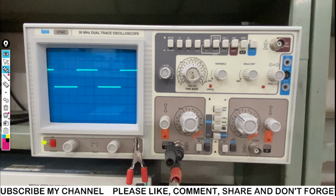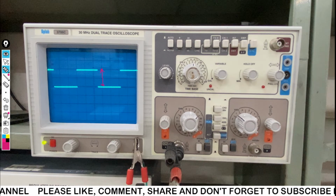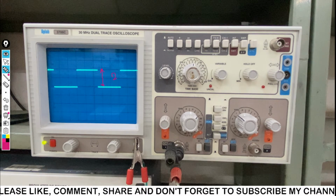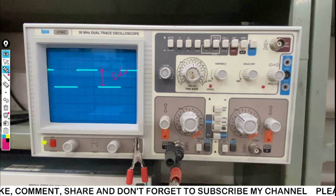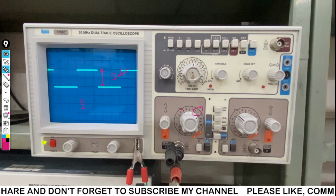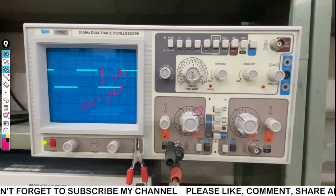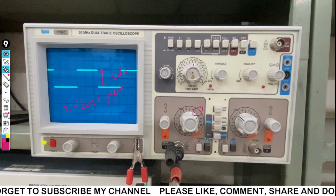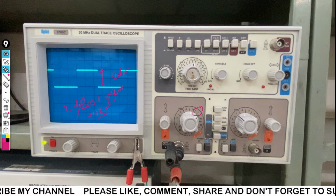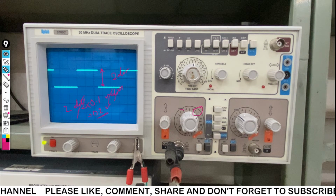So look at here how to measure the amplitude of this signal. I am going to measure the vertical distance. Vertical distance is actually 2. You can see here, these are the two divisions, and here you can see this is connected at 0.1 volt per division. So 2 multiplied by 0.1 volt per division, the divisions will get cancelled, so we'll have 0.2 volt. So this signal has an amplitude of 0.2 volt.